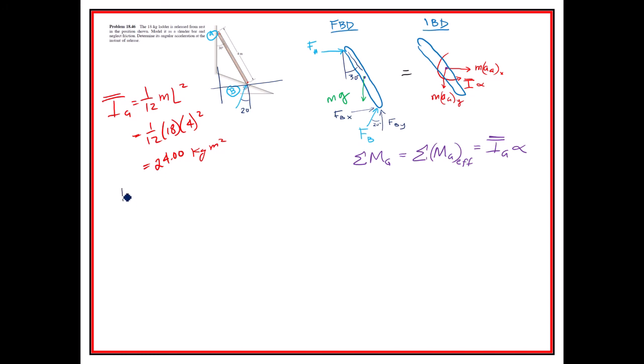So my FBX is going to be equal to FB times the sine of 20 degrees, and my FBY is going to be FB times the cosine of 20 degrees. And then the distances that I'm dealing with right here, of course, it's going to be to the center of the thing, so that just makes my life even better, doesn't it?